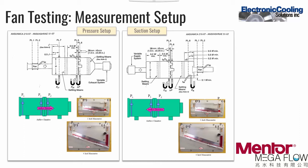The static pressure can be read off the manometer used for static pressure measurement. There is no use of the differential pressure manometer in this case. In fact, it is recommended to remove the tubes from the ports to avoid the manometer liquid gushing out. Additional points on the middle of the curve are generated by setting a specific airflow using the assistance of the variable exhaust system.